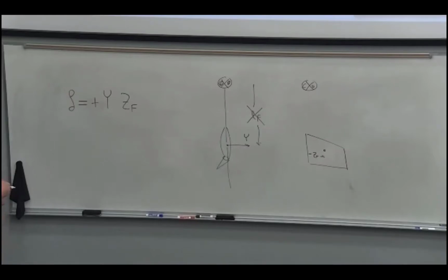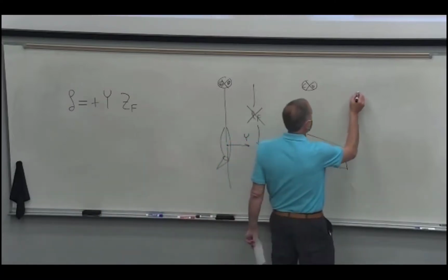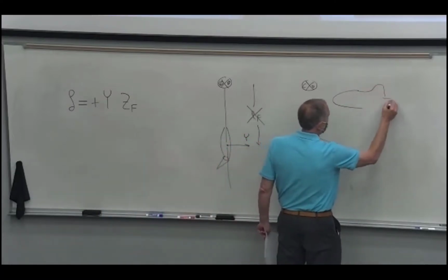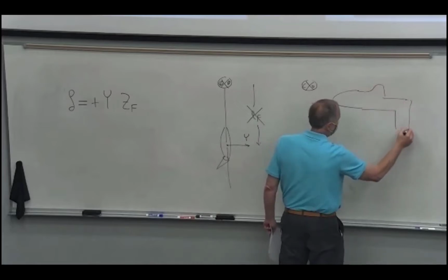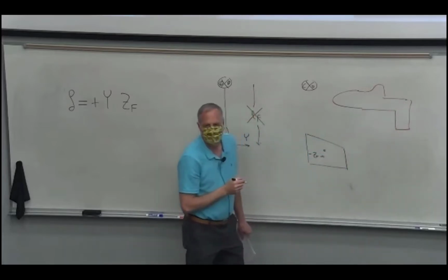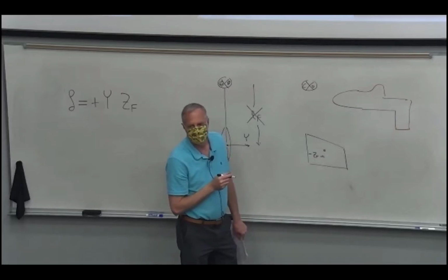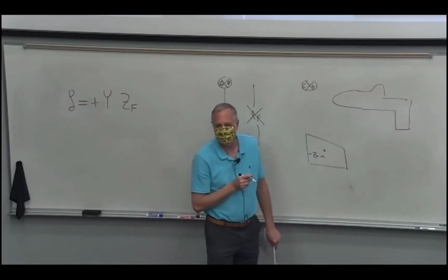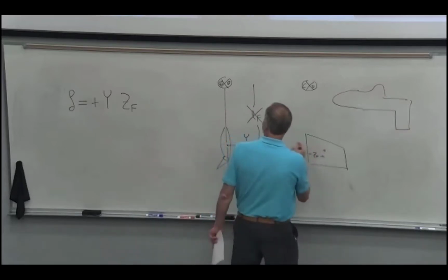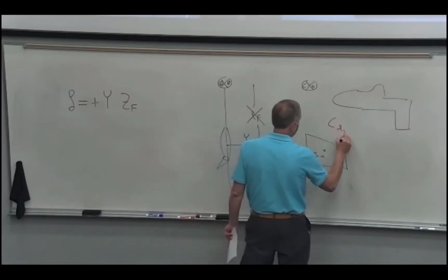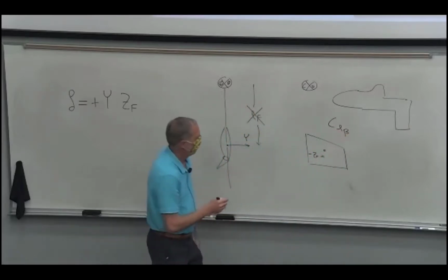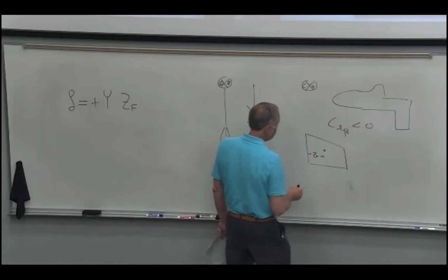Is there any reason why we don't have the vertical tail stick down? We could, right? So picture this. Here's our airplane. What do you think about that? Anybody see a problem? Yeah, you're going to hit the ground with the vertical tail, right? And the other reason is that we get the correct CL beta to roll away from the side slip, because we want a negative roll.